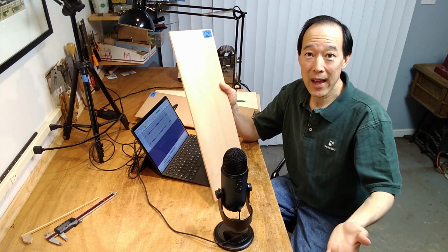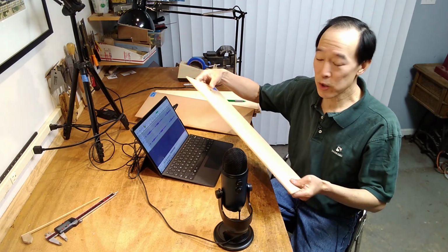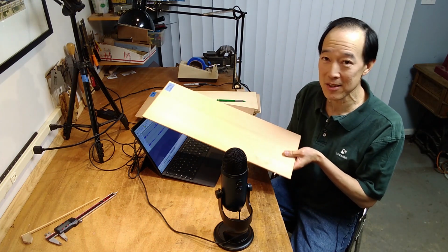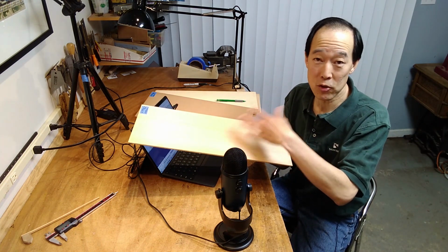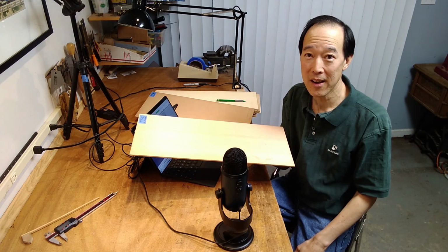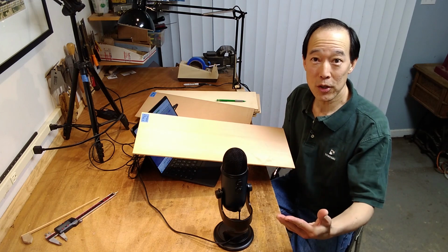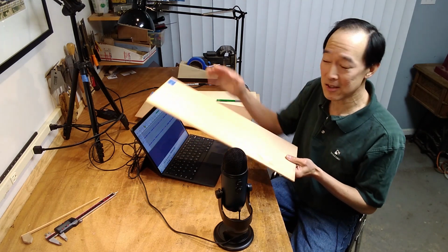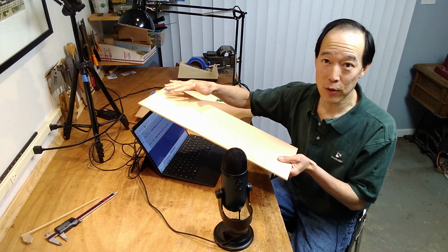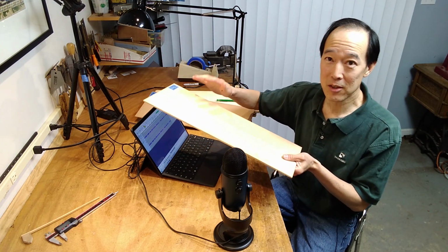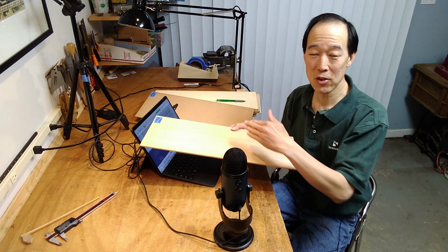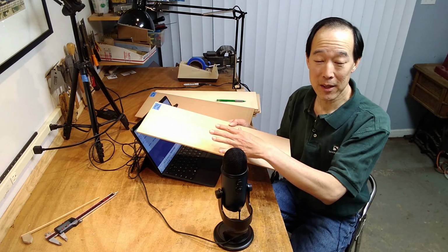All right, after that I want to know something about the stiffness, which you can flex, and it's kind of difficult to get a good read when these pieces of tone wood are maybe 2 to 3 times the thickness of the eventual soundboard in your guitar. But nonetheless, I'm going to show you how density is highly related to the stiffness in this direction, which is important because that is the direction which resists the tension of the strings. All right, so we'll talk about density and stiffness and its relationship to pitch in depth in a moment.